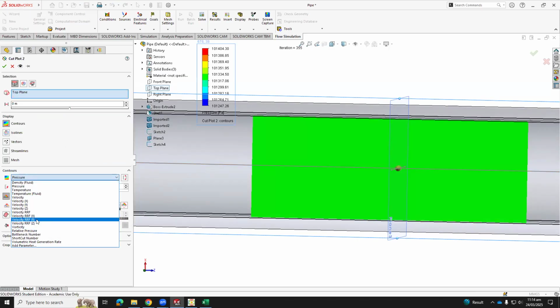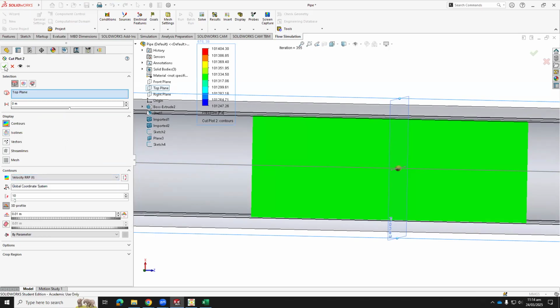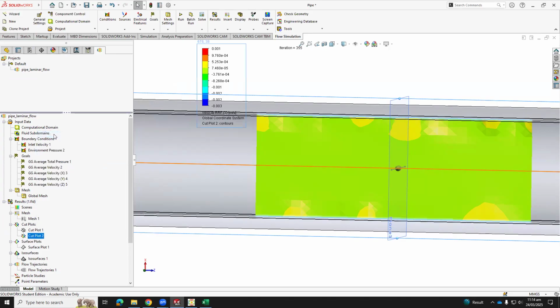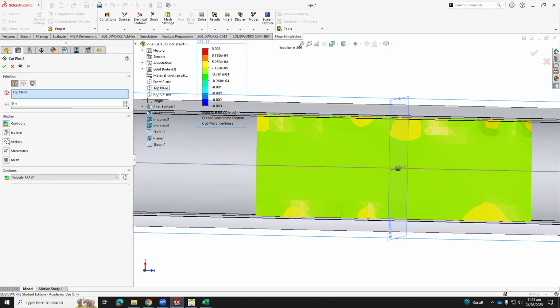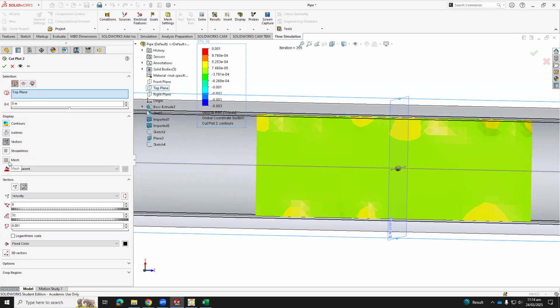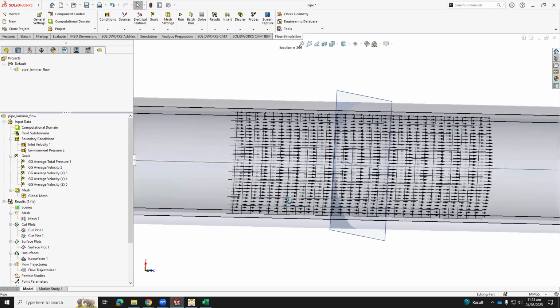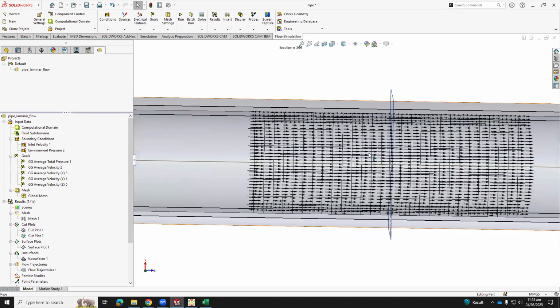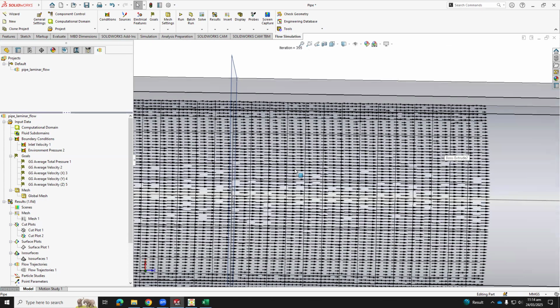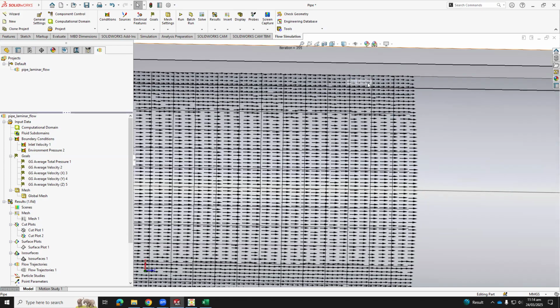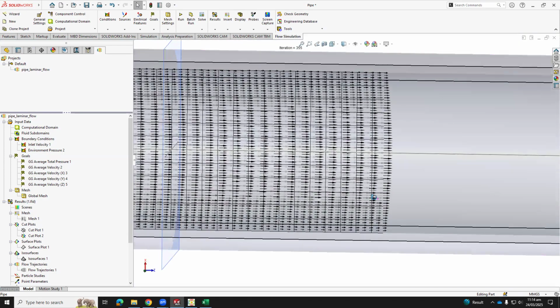In the Y, contour doesn't give me much. Stream, mesh, if I want to include mesh, transparent, velocity, fixed color. So that is kind of like I added the mesh to it, and I can see how this is very important if you want to study if this is a laminar or turbulent flow, how the flow is going with that nice profile.